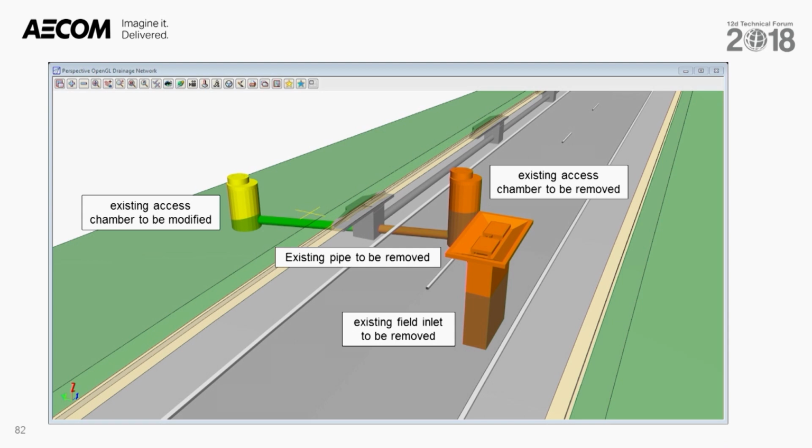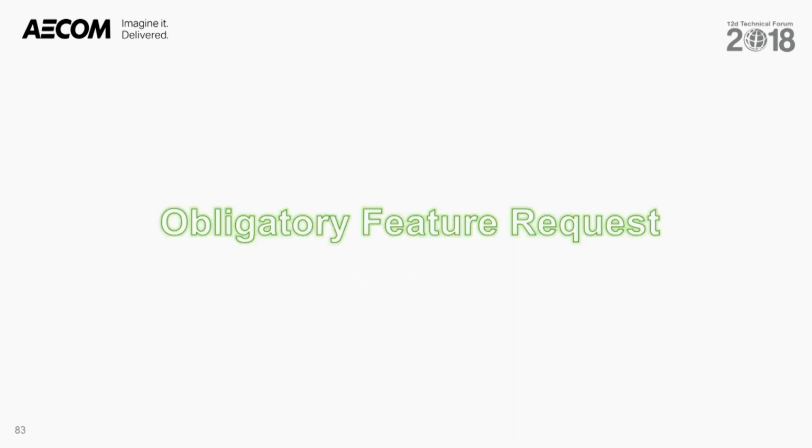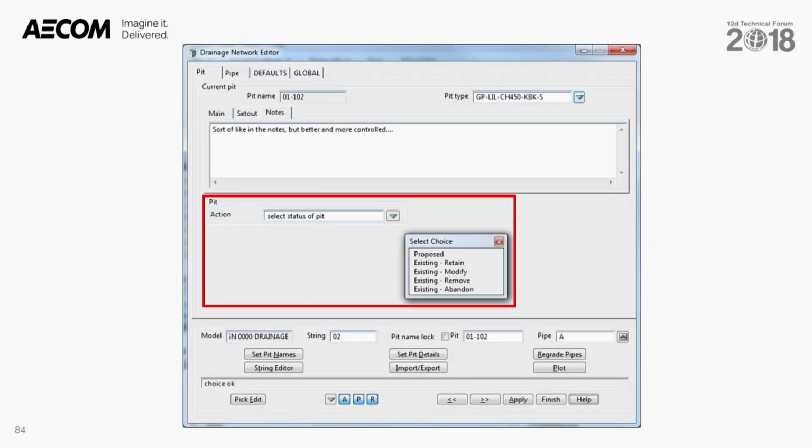You can currently do this a little awkwardly by incorporating and identifying the pit and pipe names and filtering for these in the drainage trimesh model to split these into submodels. What would be a vast improvement, though, is the ability to access custom attributes of pits and pipes through the network editor, preferably including a pick list to standardize the attributes actually used. This is far more stable than relying on manual pit and pipe names that can all be cleared with a mouse click if you do not have the right box tick.